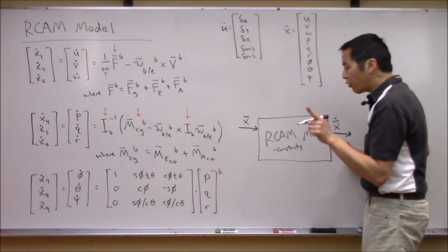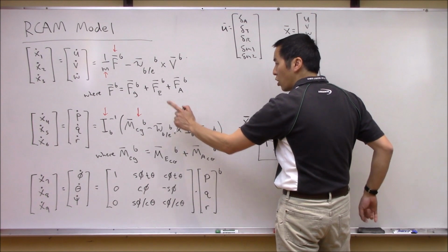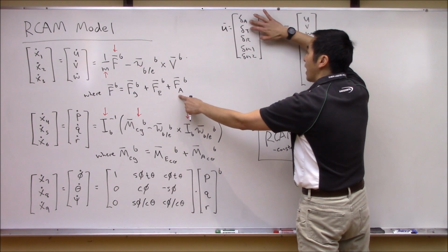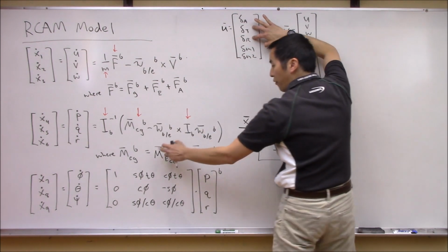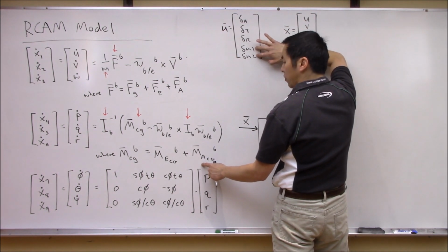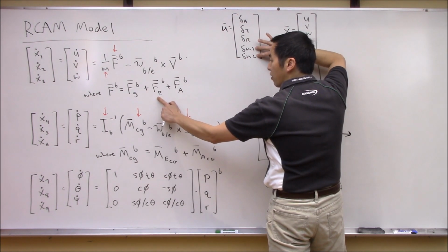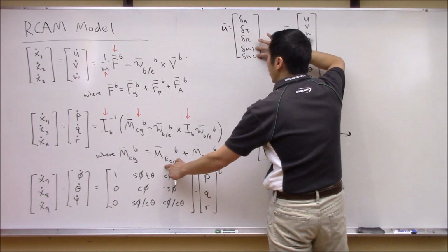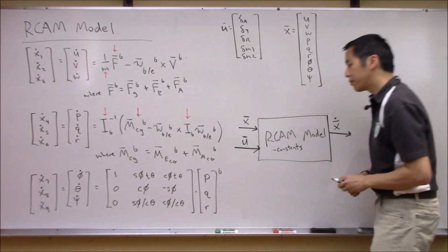dot. The other thing that we need might not seem explicitly written here, but if you remember back in our discussion, we said things like the aerodynamic forces: if you were to adjust the aileron, the tail, or the rudder, that's going to affect the lift, drag, or the side force, and it is also going to affect the moment here. And for these other two, the throttles, if you crank up these throttles, it's definitely going to change this term right here. This is the net force due to propulsion effects, and here's the net moment. So that's going to weasel its way in there. So long story short, you also need the current control inputs.